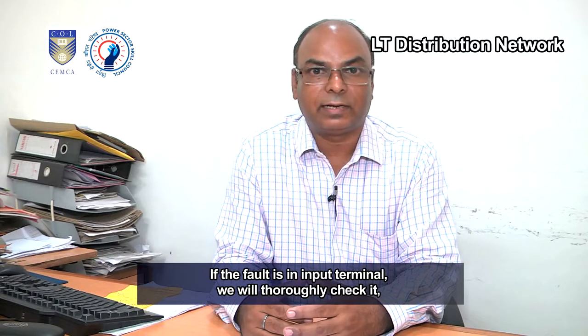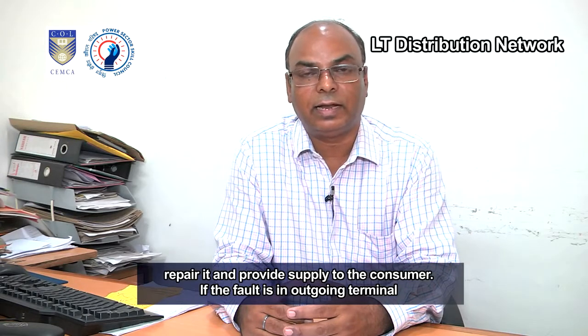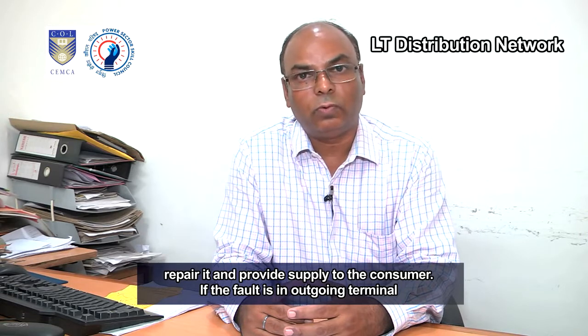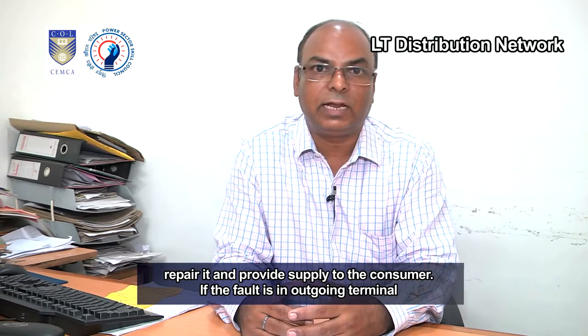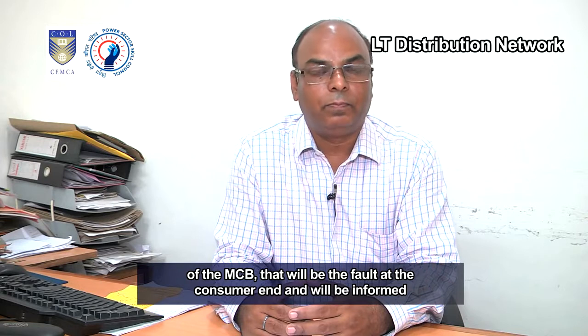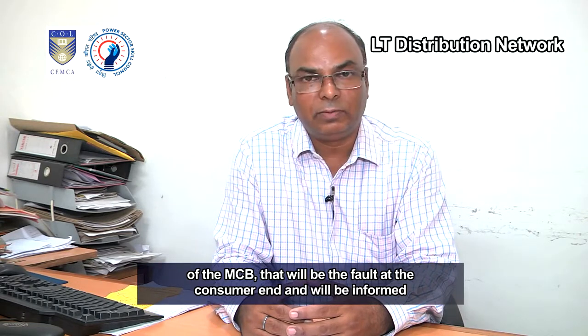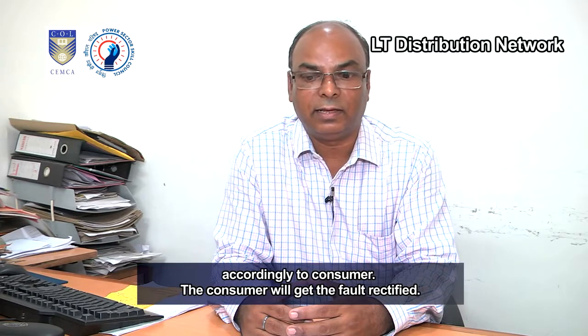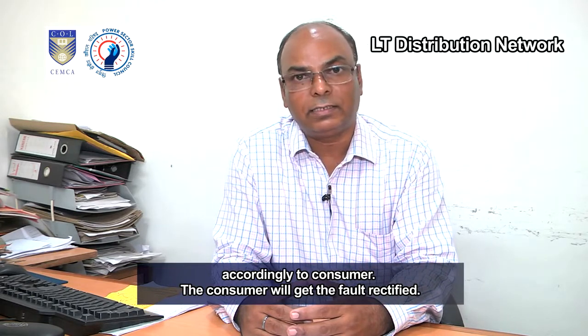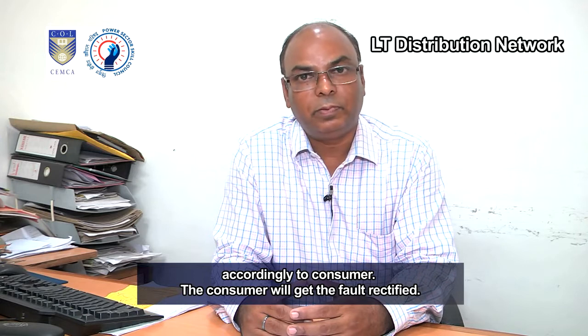If the fault is in the input terminal, we will thoroughly check it, repair it and provide supply to the consumer. If the fault is in the outgoing terminal of the MCB, that will be a fault at the consumer end and the consumer will be informed accordingly. The consumer will get the fault rectified.